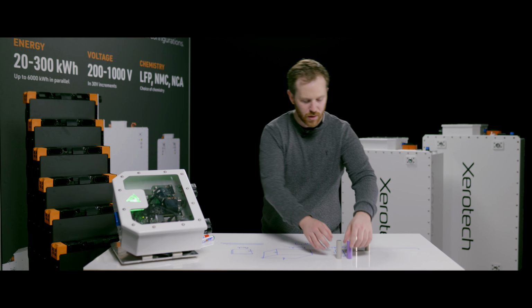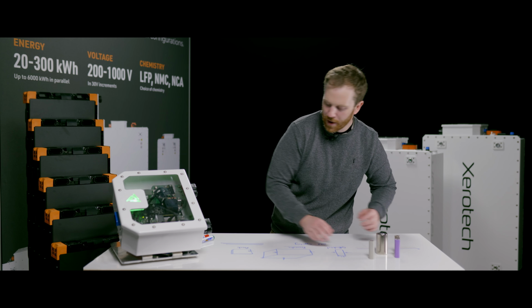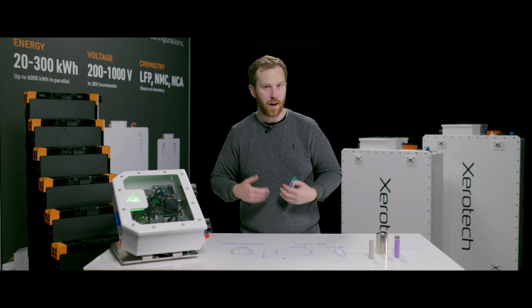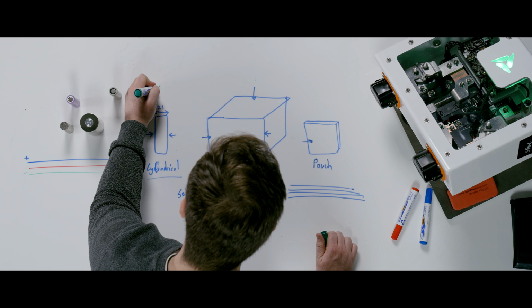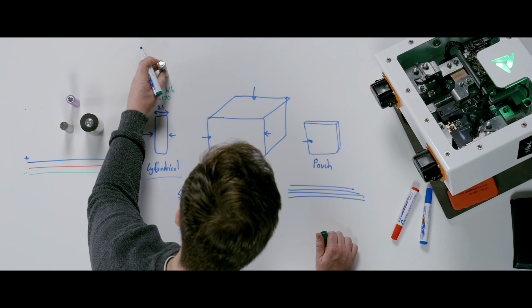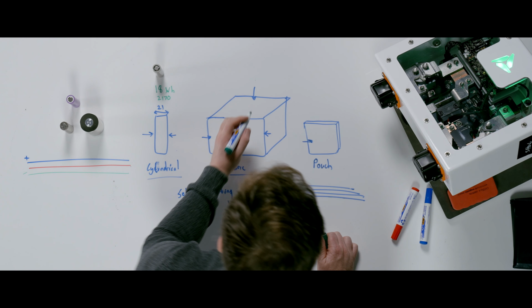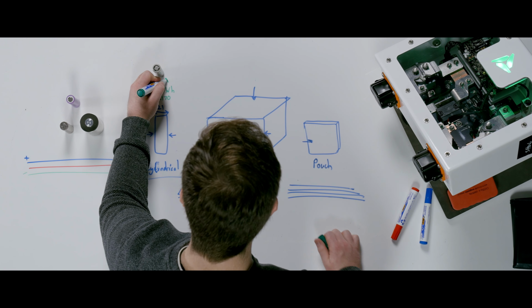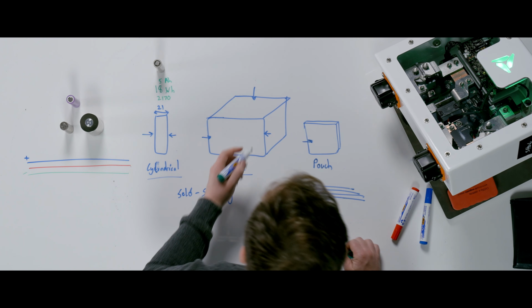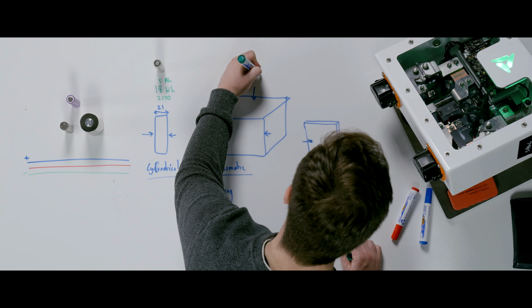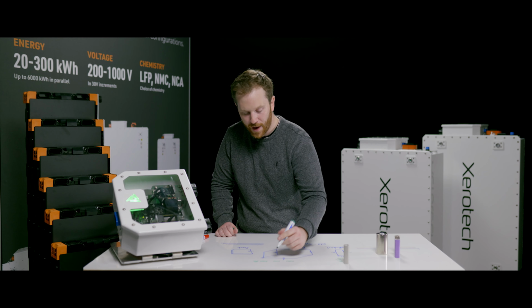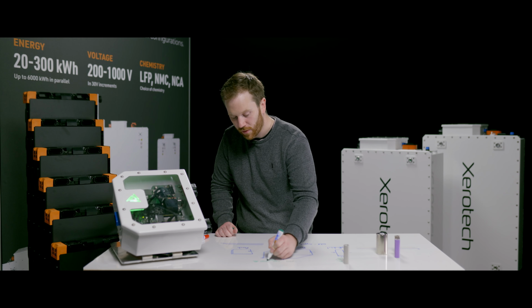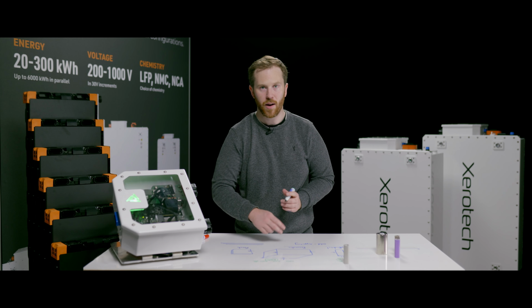And that's something that I want to consider in terms of the fundamental choice of us building our own battery packs here at Zerotech with cylindrical cells. The amount of energy in a cylindrical cell can be about 18 watt hours for a 2170 battery cell, a cell like this. For a large prismatic, because this is 5 amp hours for the cylindrical cell, prismatics can be 100, 200, 300 amp hours. That means that they can have energies in the kilowatt hours range of energy, much more energy.